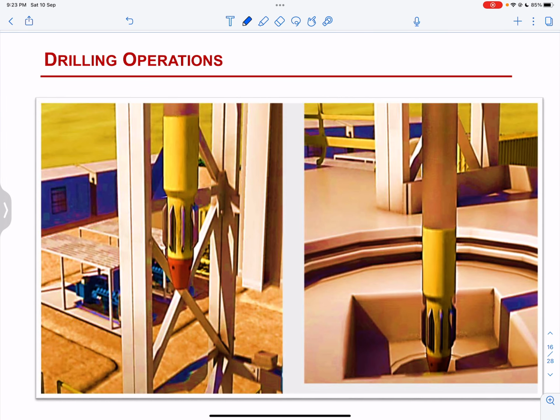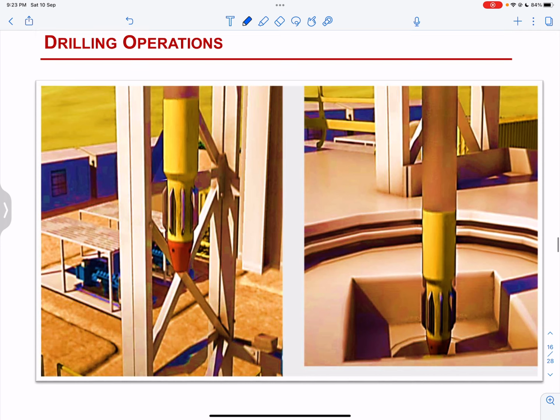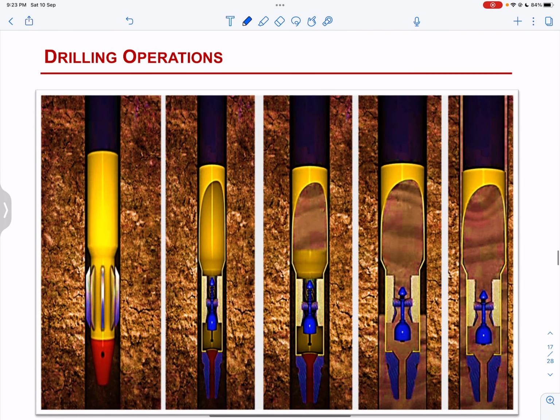To protect the integrity of the hole and to protect the surrounding deep freshwater zone, a second layer of steel casing called surface casing is installed and cemented inside the newly drilled hole. As with conductor casing, cement is pumped down through the surface casing and up along the sides of the well to provide a proper seal. This completely isolates the well from the deepest of private or municipal water wells.